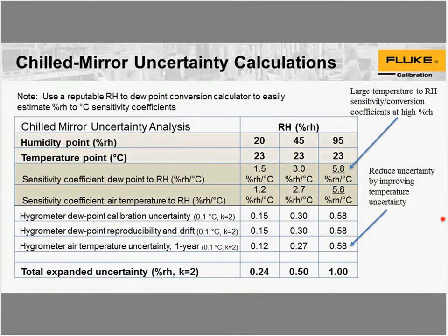It gets tricky with relative humidity. You can be measuring at a nice temperature and humidity, and then mistakenly change the temperature and quickly force the chamber into a condensation point. The controller helps you avoid that. It's not completely foolproof. There are a couple of things you can do to still put it into condensation. If that happens, you basically run it at a little bit higher temperature, a little bit above ambient, at a low humidity, and let it completely dry out before you continue on through your calibrating work.